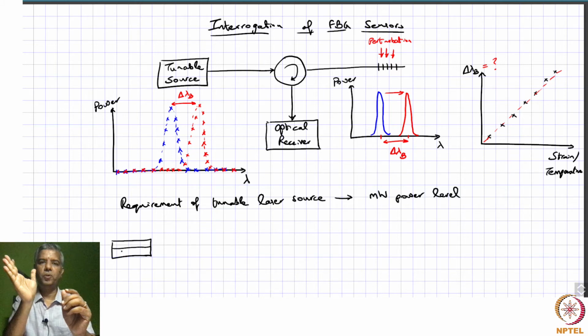That's one example. So this is the semiconductor laser, and you have a high reflector over here, but on this side you have an anti-reflection coating, and then you go into a periodic grating element, and by changing this grating angle, you can change the wavelength of the light that you get out of this.